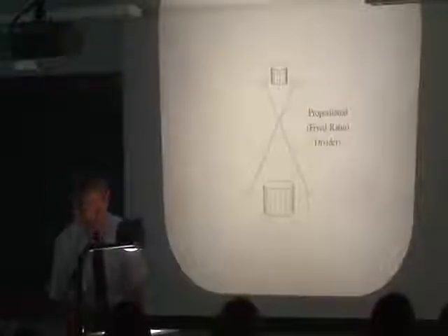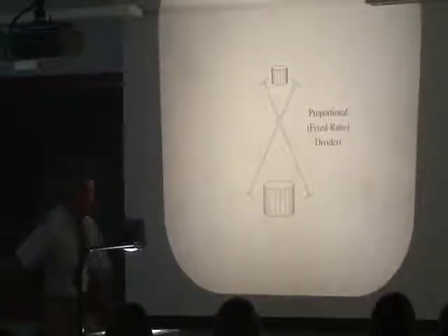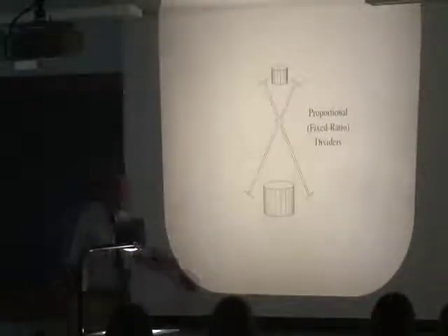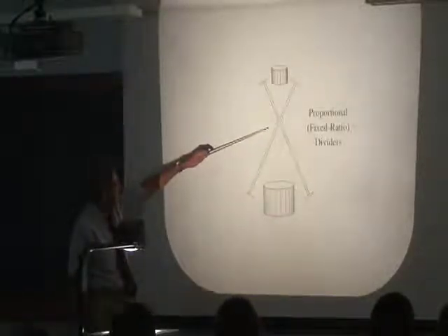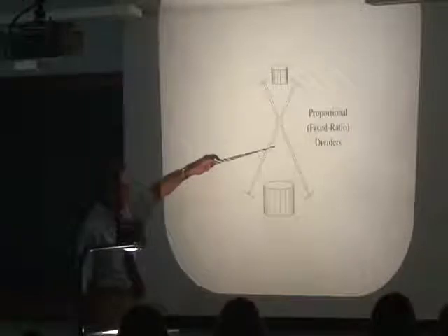And in the shop, the best you could do was perhaps 1/10 of an inch. There were no fine steel scales with engraved markings on them. There were no micrometers and things like that. The basic working tool was a proportional divider. And if you can't measure, then you work proportionally. So every shop person had a whole set of these proportional dividers. And they had various ratios. This is a 2-to-1 ratio.